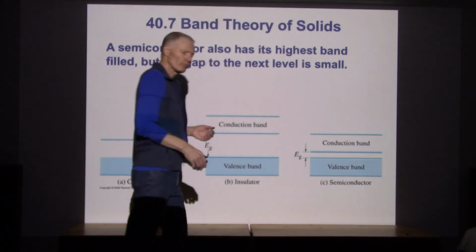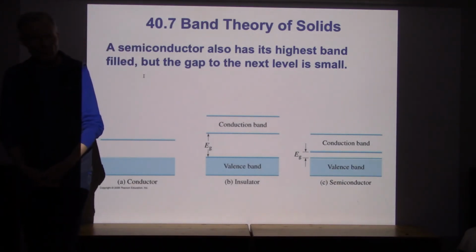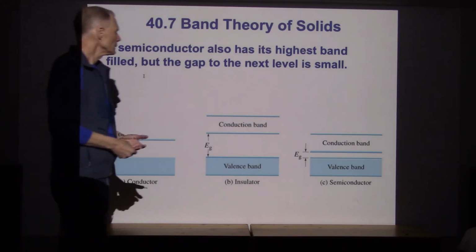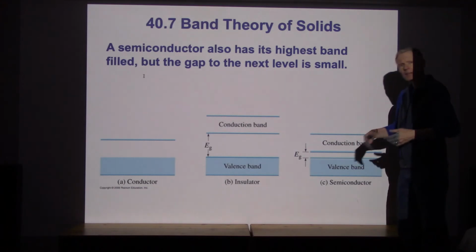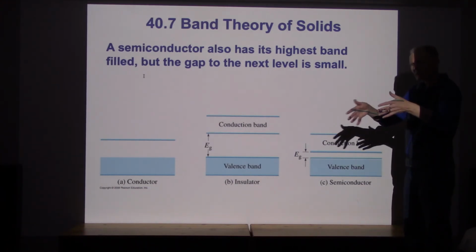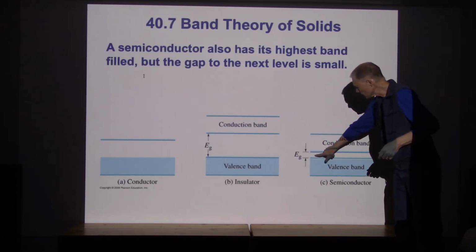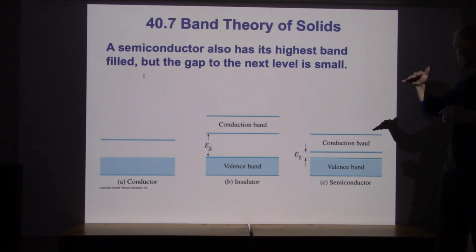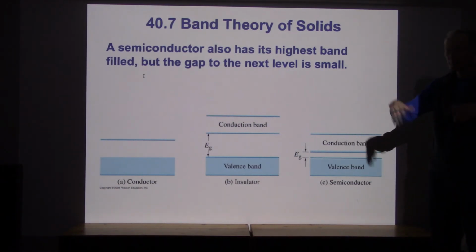Now, the most commonly thought of semiconductor is silicon. There's also carbon, which is considered a semiconductor, and germanium, some of these other elements related to carbon. We can play around with these materials. We can take silicon, for example, and put little bits of other elements in there and create intermediate quantum energy levels. So we can create a set of quantum states that fill the gap, and then we can play the game of run up the stairs.